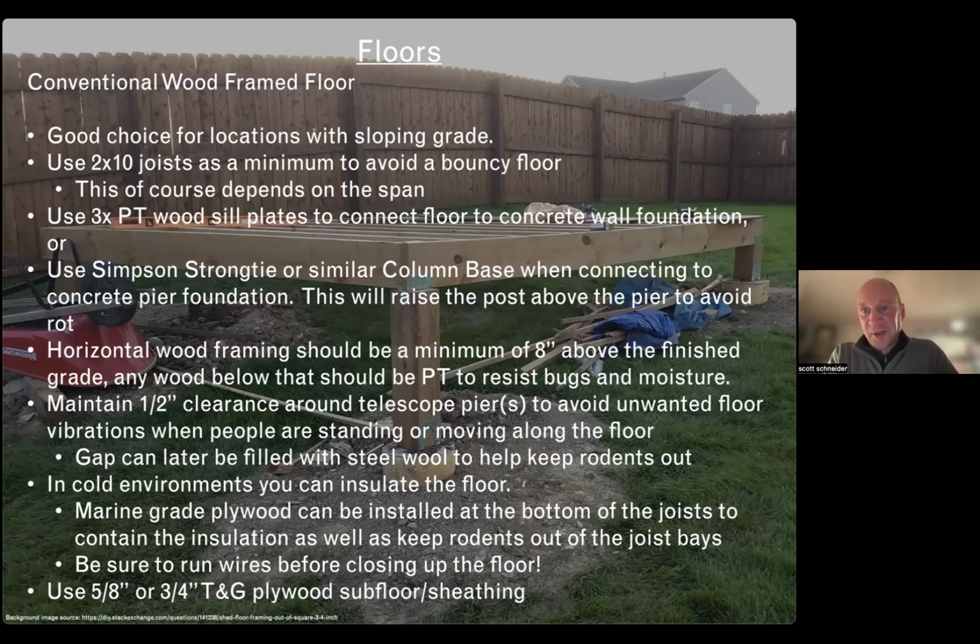It's a few things. One is how big is the mount you're putting on it? What does that require in terms of bolting and that sort of thing? And actually, I wouldn't run concrete all the way up. I would put a steel pier on top of the concrete. And the size of the concrete is really going to depend on how big the mount is.